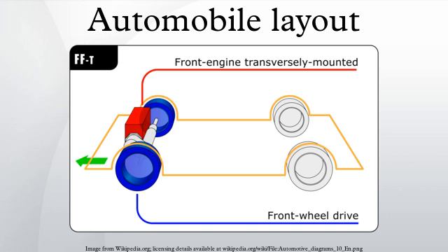The Citroen Sahara had a 4WD system using complete Citroen 2CV drivetrains at both ends of the car, such that the engine at the front powered the front wheels and the engine at the back powered the rear wheels. A through-the-road hybrid vehicle uses a conventional piston engine to power two wheels, with electric motor generators on the other two wheels, giving a form of part-time 4WD.